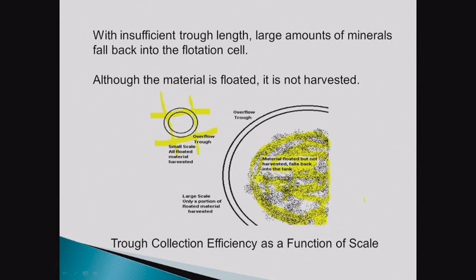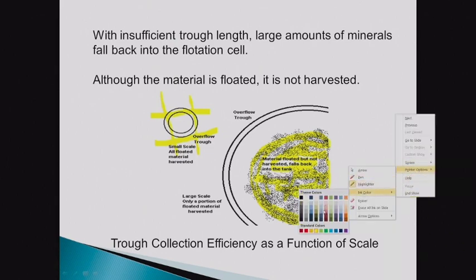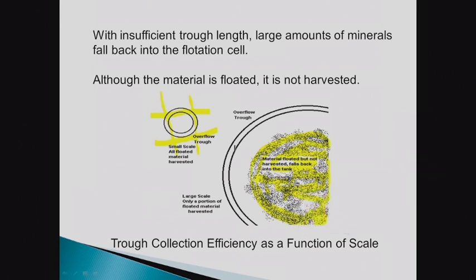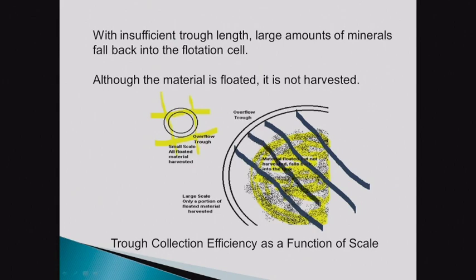Because this was a highly efficient one. Then I would choose another highlighter color. Let's try that color. I would put a weir here, another overflow weir here, maybe another one up here, a sneaker one right in there, and one there, and there.